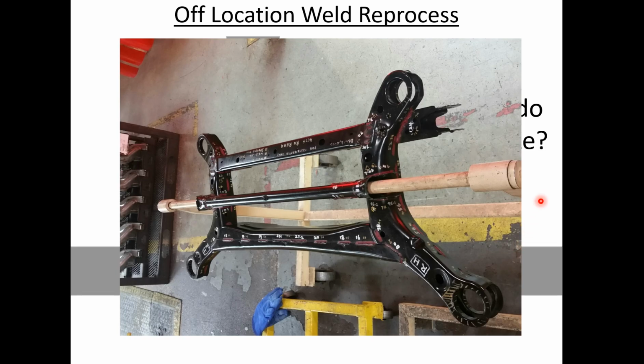So here's a good example of something I've done, and this could be a part of this presentation that's more for engineering and quality than the people that are performing the work. But you guys need to know about this device too. As the people performing the work, you need guidelines for what this component should do. This is very typical of the organization of how to identify what welds are where. Within this engine cradle, the engine cradle RU, Chrysler Pacifica, there's a whole bunch of welds, and what we've done is identify them by the weld number. You know what side they come from: the right hand's even, and the left hand is always odd.